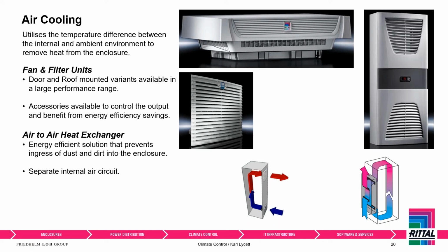We also have air-to-air heat exchangers. Now, the good thing about an air-to-air heat exchanger is it still utilizes that difference between internal and external temperature. However, it's a separate internal air circuit. So what's happening is it still acts like a fan and filter, but it's not constantly pulling dirty air inside the enclosure. So if you know you have a dirty environment, but it's cool enough to use air cooling, your air-to-air heat exchanger might be your man. Okay, so keep that in mind. It can be a nice handy solution for you.